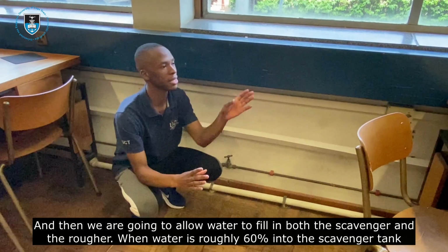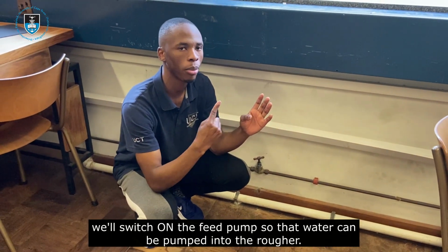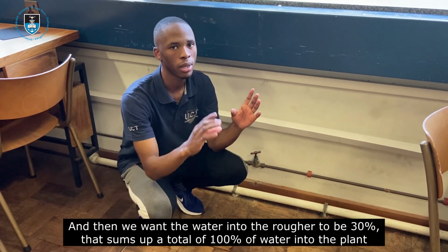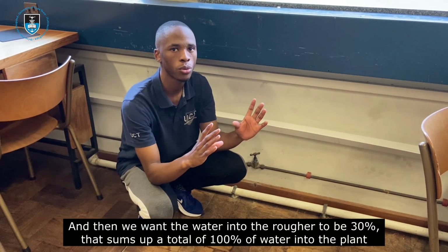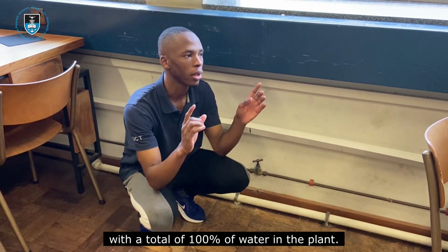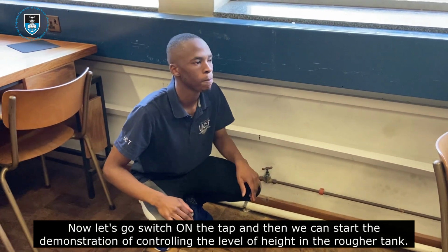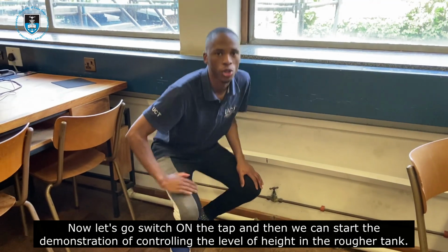When water is roughly 60% in the scavenger tank, we'll switch on the feed pump so that water can be pumped into the rougher. And then we want the water in the rougher to be 30%. That sums up a total of 100% of water in the plant, so that we can control the height of the rougher tank with a total of 100% water in the plant. Now let's switch on the pump and the tap, and then we can start the demonstration of controlling the level of height in the rougher tank.